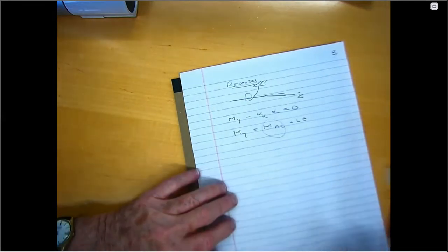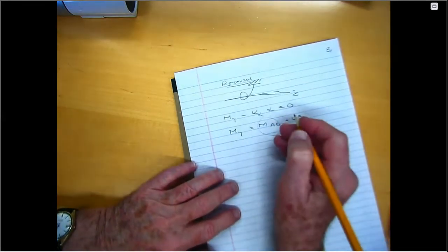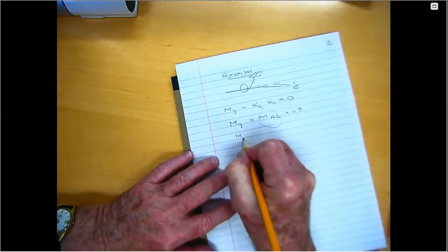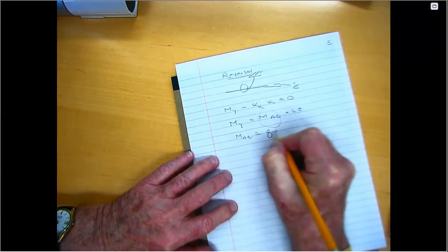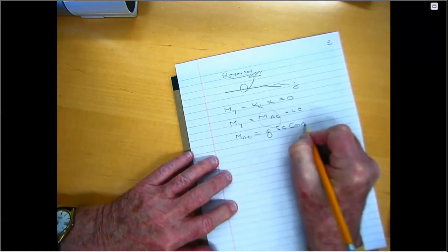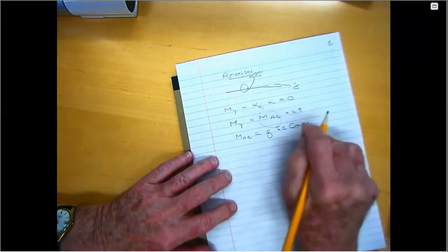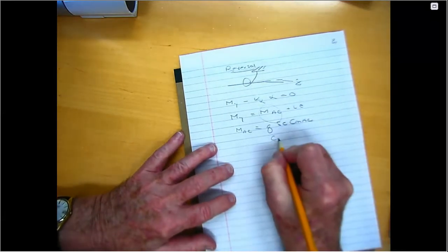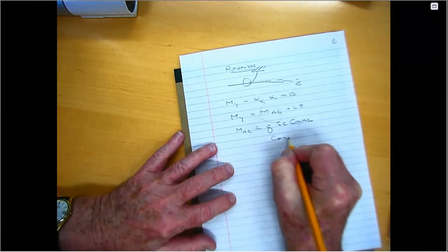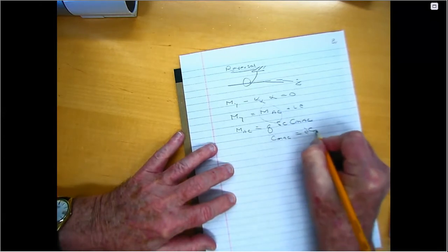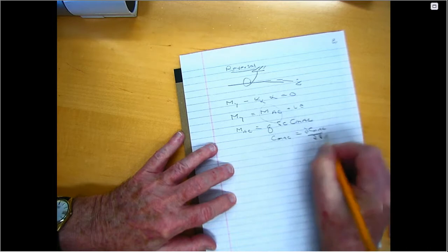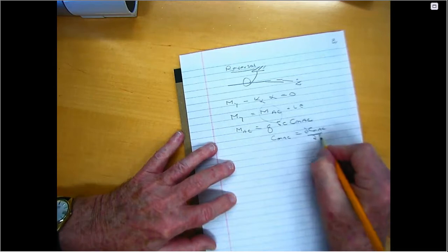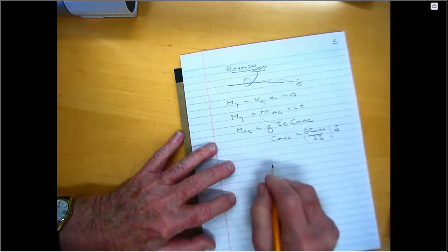For the moment, we only need the moment, right? And the lift. Okay. So again, we're going to write MAC as QSC times CMAC. But whereas before, MAC was a constant, just some number, now CMAC is some coefficient that we, by tradition, call dCMAC d delta, times delta, right? It now depends on delta.